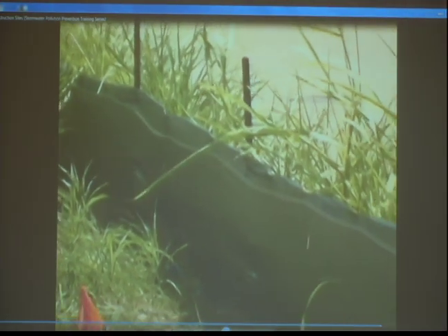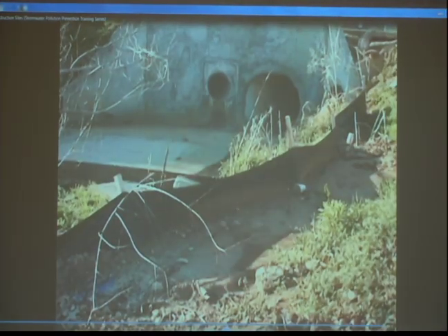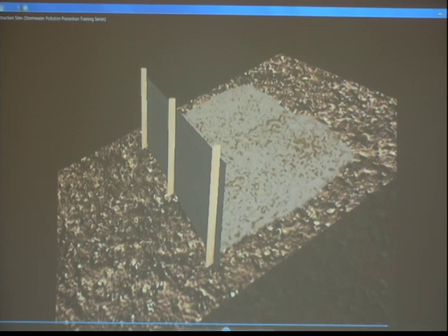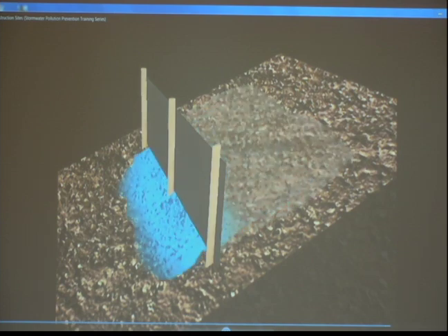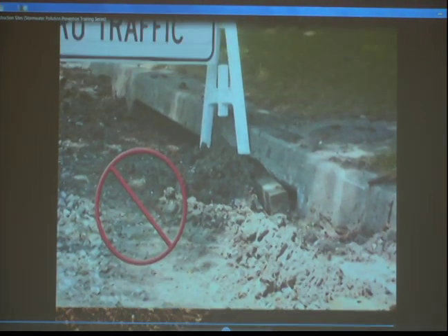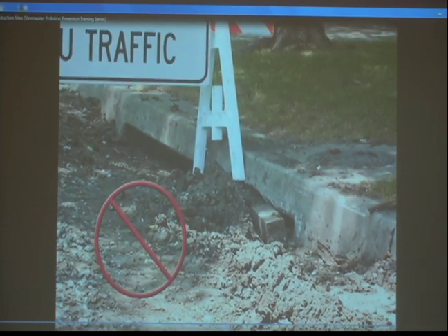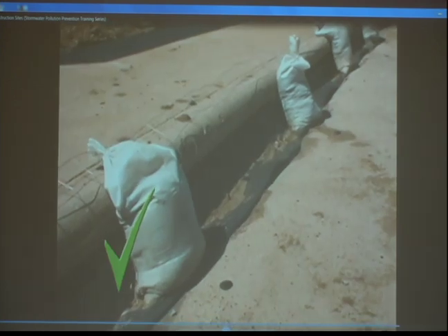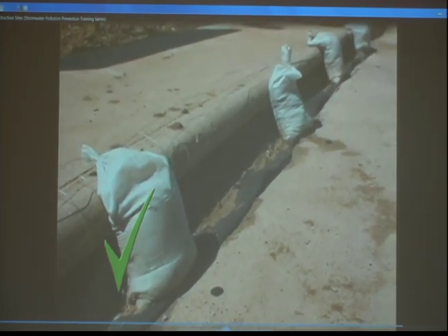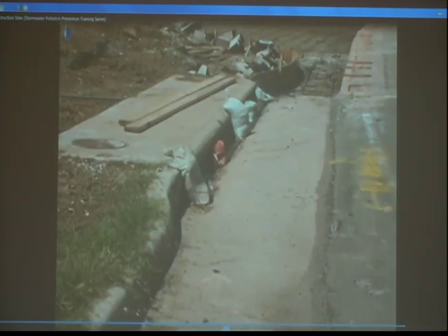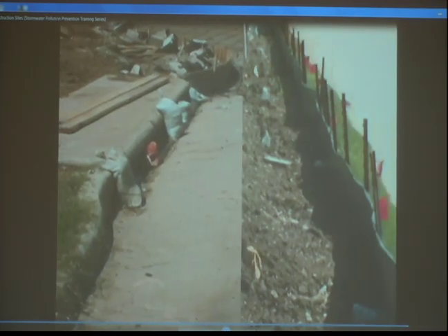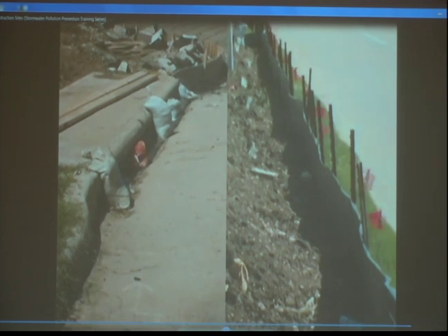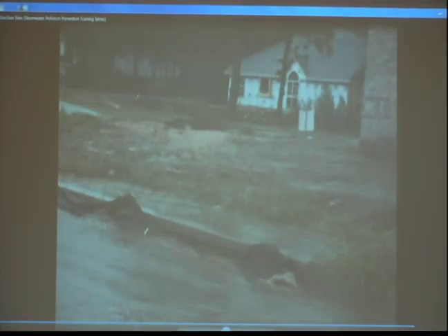All of these methods use the same principle. They prevent silt runoff by slowly releasing the water after the sediment falls out. Additional sediment control can be achieved by placing wire-reinforced filter fabric directly in front of the storm drain inlets. This method must always be used in conjunction with other on-site methods. Otherwise, there will be too much sediment in the water and the storm drain will clog.